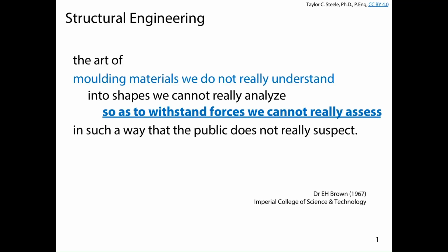So far in this course, we've been focusing on uncertainty around loads and resistance. We talked a little bit about structural steel the first day, how we can calculate what we expect the resistance to be, but there'll be some variability around it. We talked about how structures work, and so we looked at gravity framing, concepts of tributary areas and widths for joists, girders, and columns. And for the last few days, we've been talking about gravity loads.